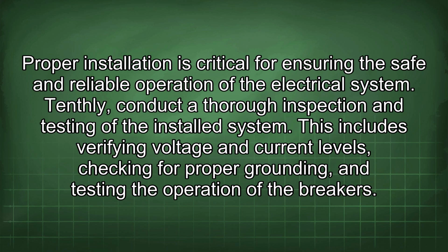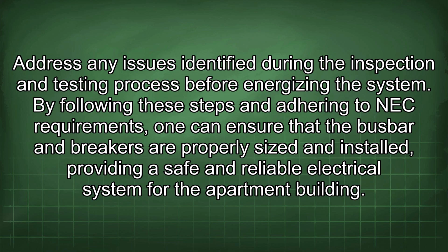Proper installation is critical for ensuring the safe and reliable operation of the electrical system. Tenthly, conduct a thorough inspection and testing of the installed system. This includes verifying voltage and current levels, checking for proper grounding, and testing the operation of the breakers. Address any issues identified during the inspection and testing process before energizing the system.